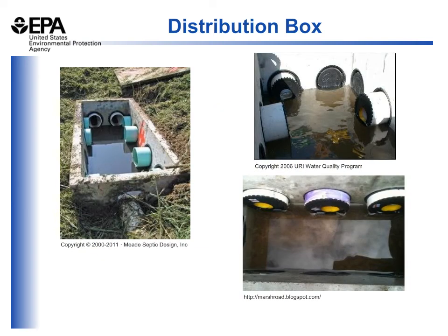The second major component of a septic system is the distribution box, and this is used to accept the effluent from the septic tank and disperse it evenly across the leaching field or leaching trenches. The idea here is to not have the effluent come from the septic tank and discharge all in one location within your dispersal facility, but to take that effluent and spread it evenly around the disposal facility. This maximizes the life of the system and makes sure that one area is not overloaded while others are not receiving any effluent. Often this is done with one pipe from the septic tank coming into the distribution box and 3 or 4 or more outlet pipes heading from the distribution box out to the leaching facility.